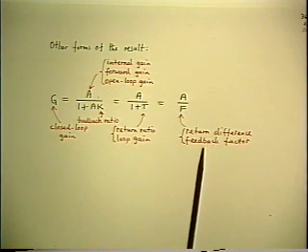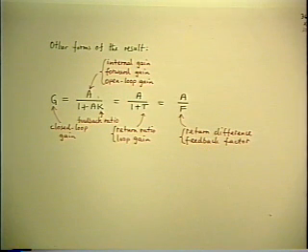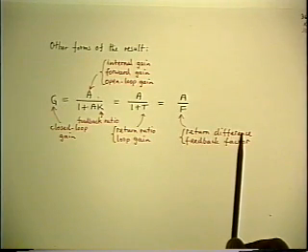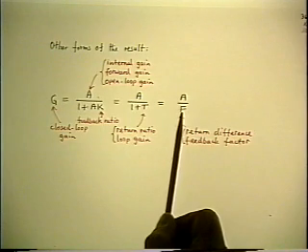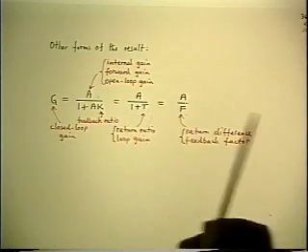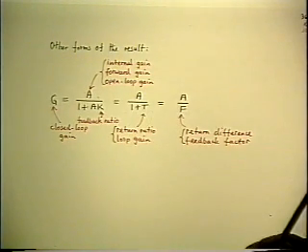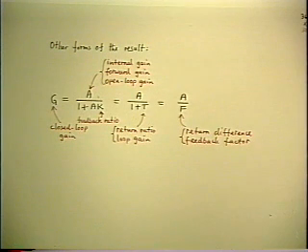Another phrase would be the gain reduction factor due to feedback. Another term is return difference. And you might say, since F is 1 plus T, why isn't it return sum? Well, it's a matter of choice of original polarity definitions.